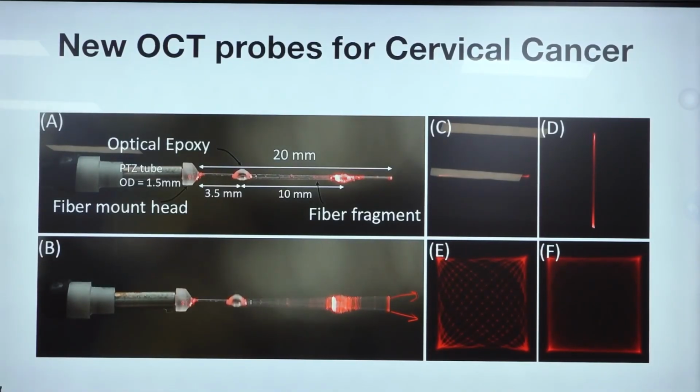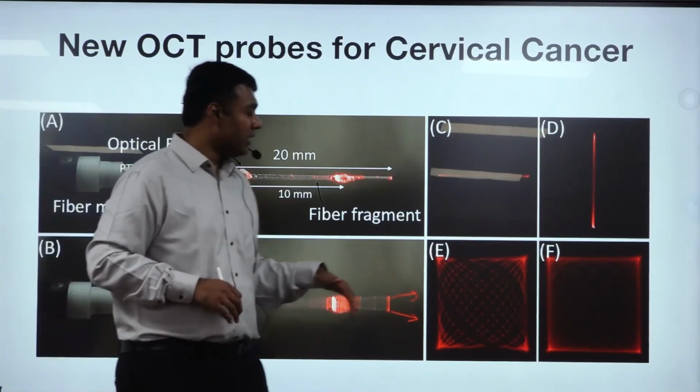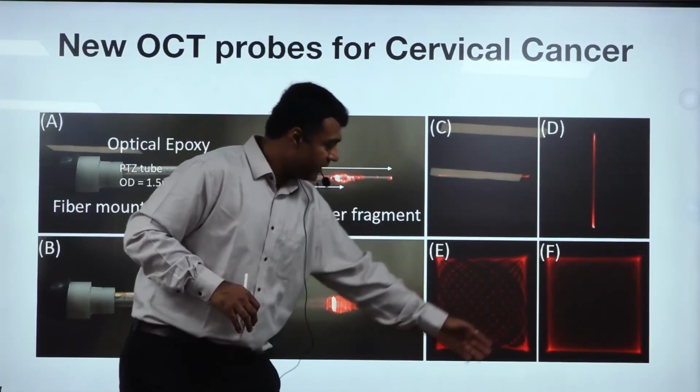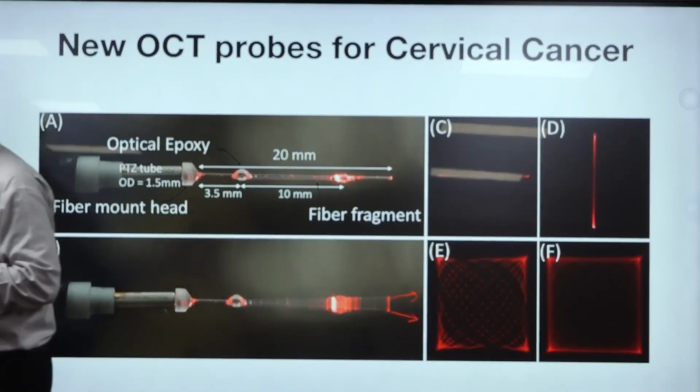If you have a sinusoid along the x-axis and a sinusoid along y, it's actually harder than you think, because for the Lissajous pattern to be stable, the frequencies have to be integer multiples of each other. But we achieved that through some waveform generation mechanisms, and you can create a pattern of this sort.